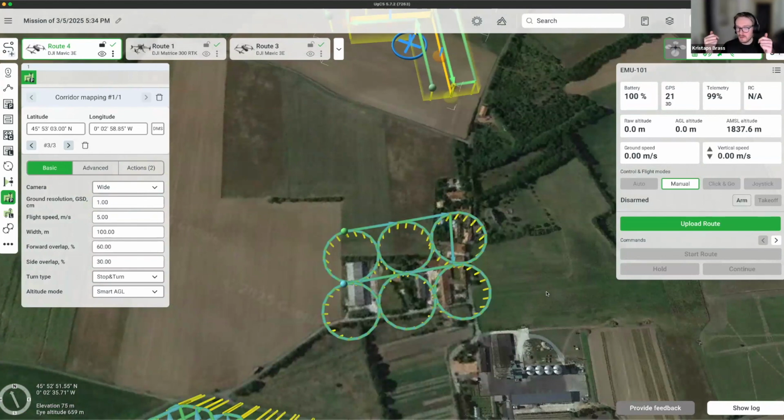That's because the way those smart oblique missions are constructed in Pilot 2 for that drone, it overextends. So let's say you have this area, basically it triples the total length in each direction with the smart oblique, which, if you want to fly low enough to collect detailed data, might simply not be possible. I've also faced this challenge when having to scan an area surrounded by trees. Then it's simply not possible to fly low enough without risking the drone crashing into trees as it does those insanely long overshoots. So in that case, circlegrammetry is better.